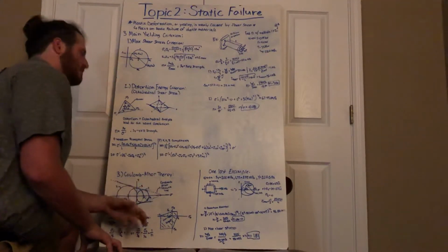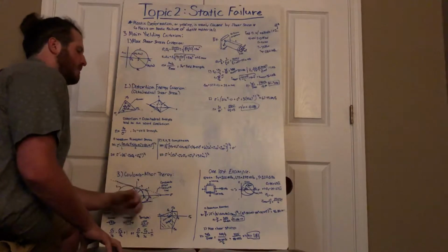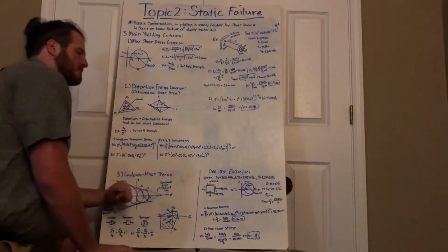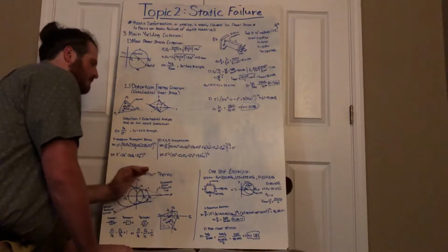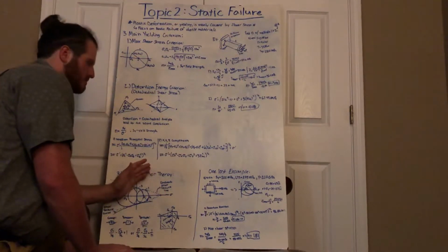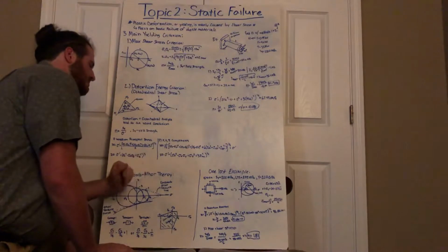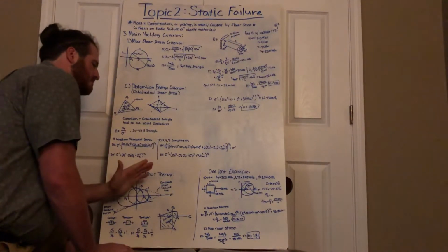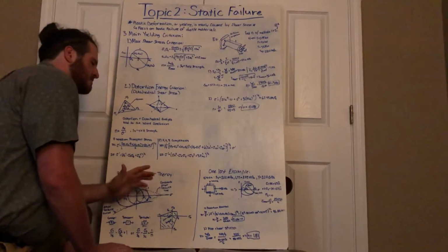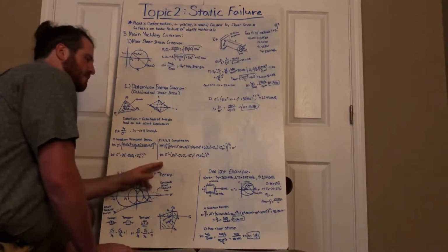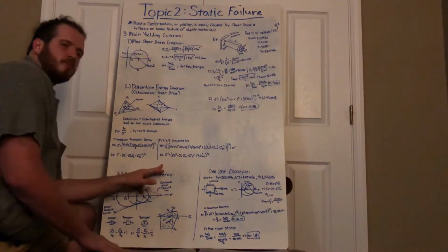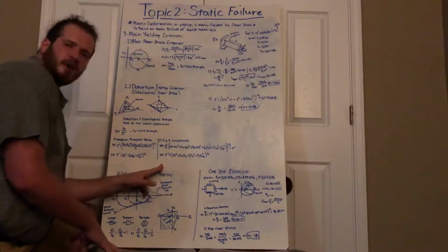That quantity, all of that to the 1/2 power, except the 1 over root 2 is outside of that. That's a little complicated, but luckily we have more of a 2D analysis, which works more in our favor. That 2D analysis will be sigma prime equals sigma x squared minus sigma x sigma y plus sigma y squared plus 3 tau xy squared, the entire thing to the 1/2 power.